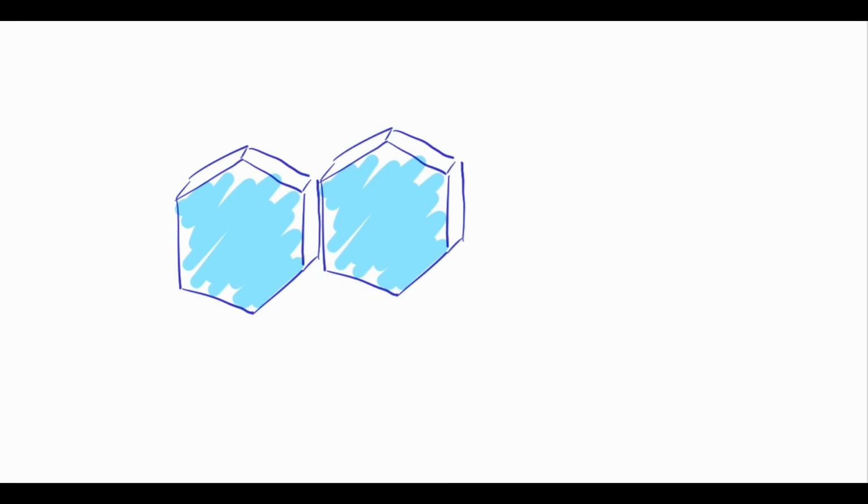PCB selection was something that I doodled on for a while. I wanted to mount the LEDs to the sides of the tiles, where the grout would ordinarily be. The back of the tile is opaque, and besides, if the LED was shining through the back of the tile, it would just look like a spot of light in the middle of the tile, rather than really making the whole tile glow. Originally, I thought I'd have a thin, long board that would go sideways in between the tiles, with all the components on either side of it.